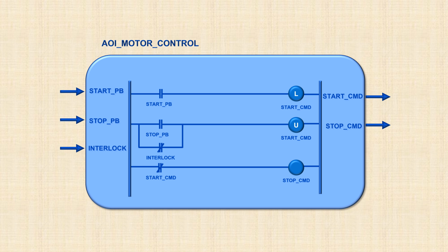Here is the template for generic motor logic that is enclosed inside a block. Now, this is a template only and can't be directly used for a motor. We will declare an instance of this AOI for a specific motor and connect that instance with corresponding motor tags.